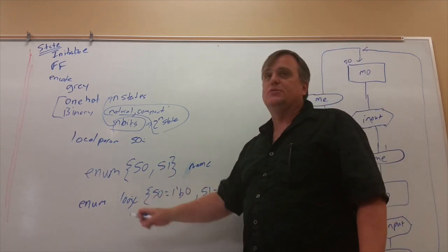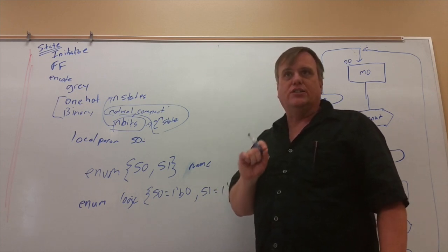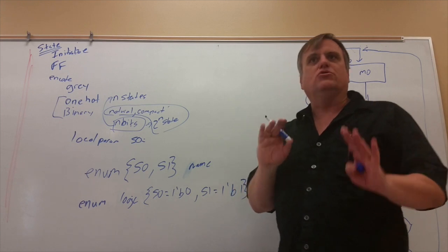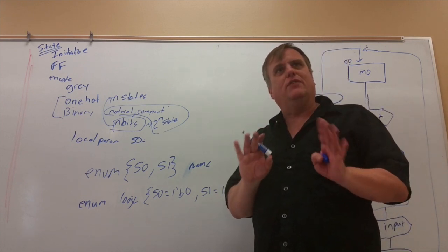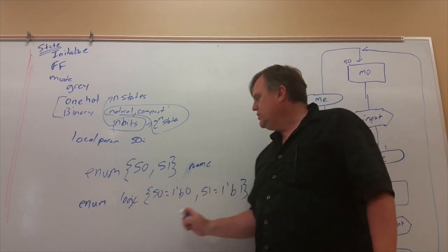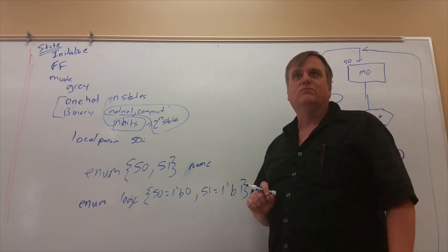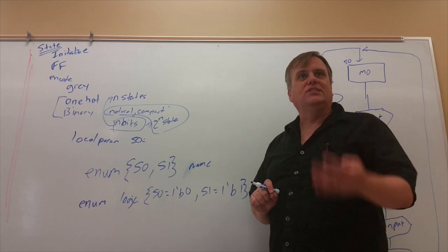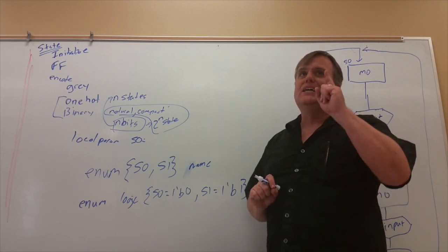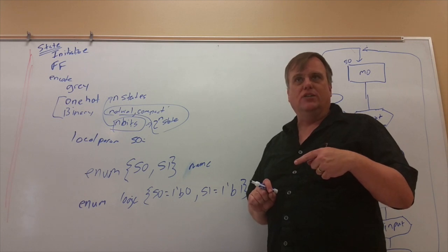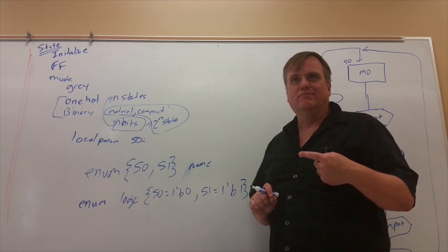One of the unique things about logic: we said we're going to use logic instead of wire or reg. And I kind of hemmed a little, because there are always a few caveats. Logic presupposes 0 and 1 is what you're designing for. X and Z are allowed, but they are going to flag you with a problem, because you can't synthesize those.